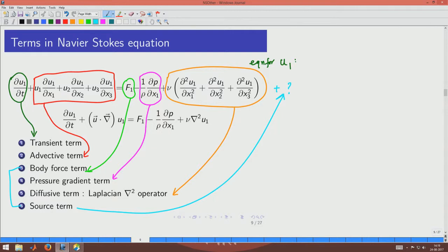Okay. And if you want to look at this equation in the vectorial form, then you would see that there is a material derivative term here, there is a grad term here, and there is a Laplacian term here. So, having derived the Navier Stokes equation, if you now want to look at how this equation would look in other coordinate systems, perhaps we can just look up these operators in other coordinate systems, substitute and proceed.